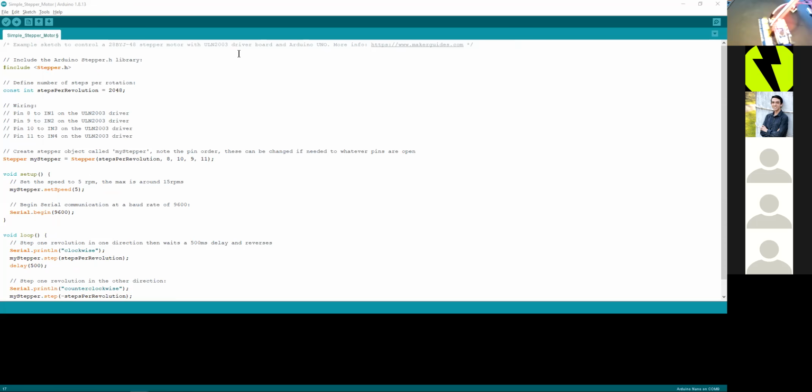Starting with that, as you can see I have the stepper motor connected to the block right here, power and ground going to these two pins, and then inputs 1 to 4 are going to pins 8 to 11. Now, to run the program, you also have this program in your zip folder I sent you. You just open it up, and then you hit compile.